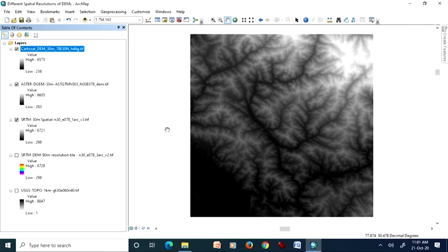You can check it with 10% randomly selected points kept in a separate file, and later, once you have found which interpolation is the best, you can employ all 100% of the points. But here you need some control points to check. If they are not available, then relative checking can also be done using random points.